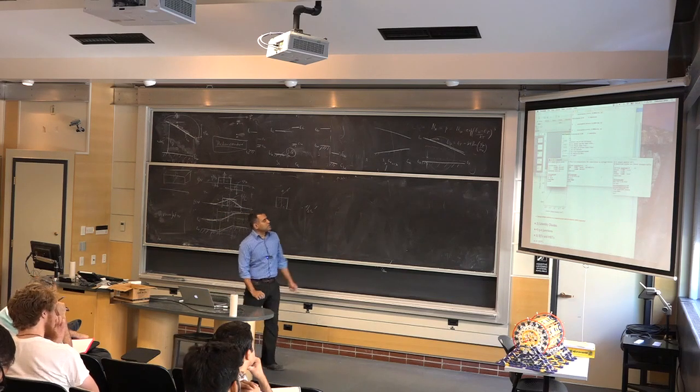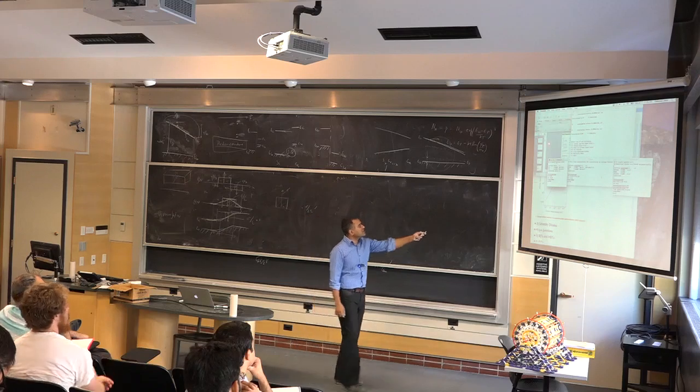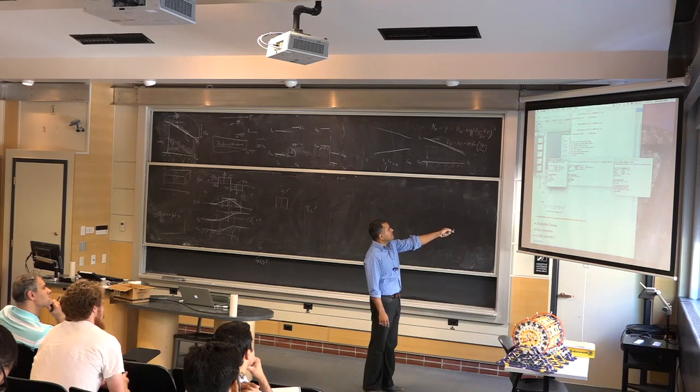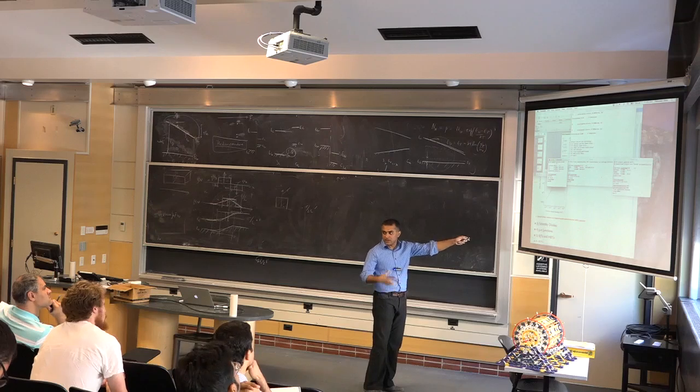Here are some examples of structures. Here's a silicon PN junction diode, silicon with doping densities of acceptors and donors of 1e16. And then you ask it to calculate the band diagram, the charge, the field, all that stuff, and it will do it all for you.